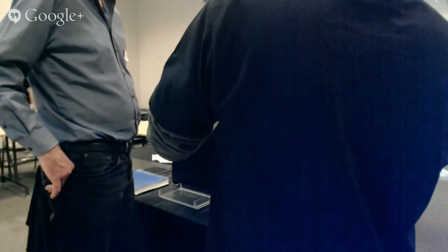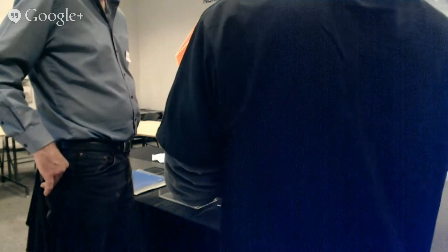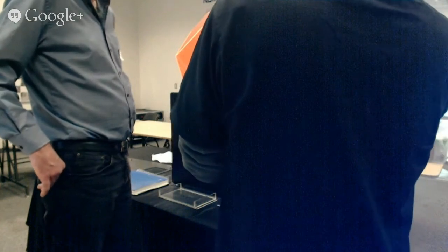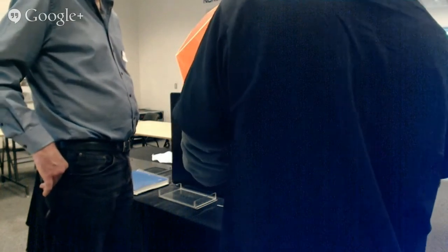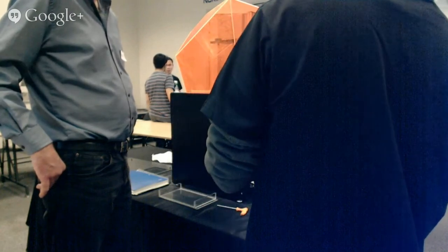So I have a bunch of supports that come at an angle out from here, sticking onto the attachment layer, and that helps hold the corners on. Because once one corner starts to come off a little bit, that'll grow. So you really need to make sure that detachment just never happens. That's what I did on both ends, and that helped a lot.